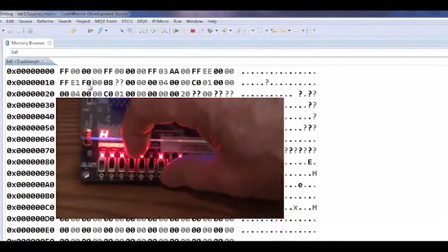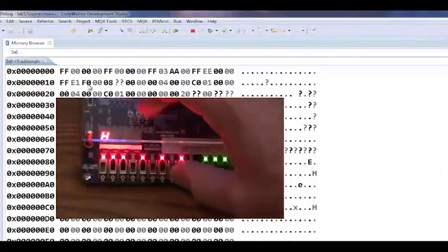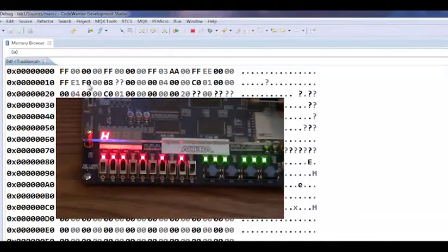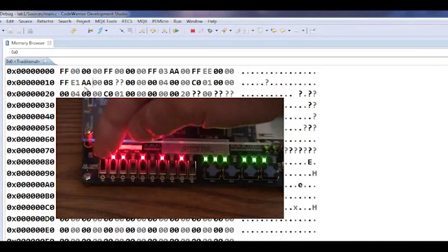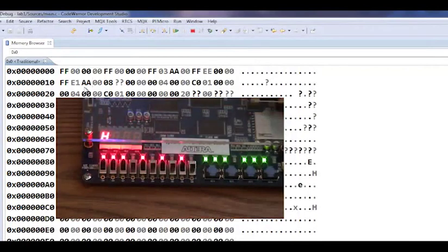What I'm going to do is change this to 1, 0, 1, 0, 1, 0, 1, 0. Now, nothing has changed on our screen here, but if I double click on this number here and I pump in 0, 0 and hit enter, you can see that it's now changed to AA, which is exactly what the switches are reading. So how do we change the upper two switches? Well, let's put them both on. And what that should mean is before it was a 0, 1, now it's a 1, 1. So what we should see now is this number changing to an E3. So let's double click on here and punch in 0, 0, and indeed what we're going to see is E3.